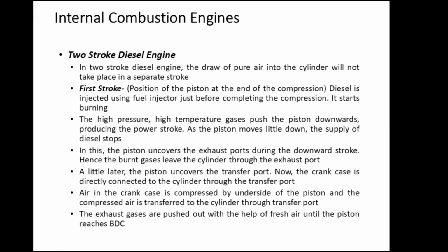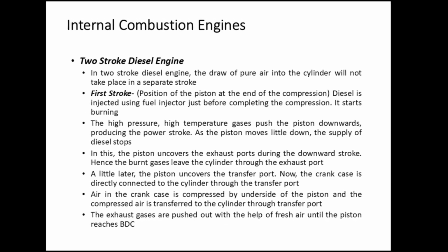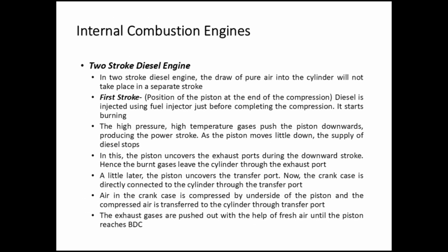Internal combustion engines. Two-stroke diesel engine. In two-stroke diesel engine, the draw of pure air into the cylinder will not take place in a separate stroke. First stroke. Position of the piston at the end of the compression. Diesel is injected using fuel injector just before completing the compression. It starts burning. The high pressure, high temperature gases push the piston downwards, producing the power stroke.